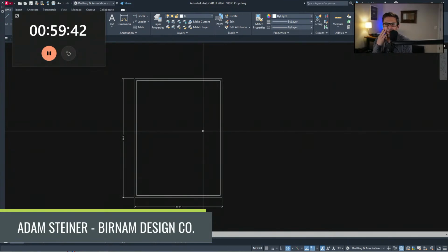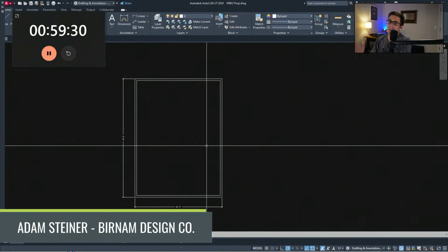So as weird as this sounds, typically I start with the bedroom area. I don't know, just blocking that off in my mind seems to make a little more sense, and then working backwards, kind of backing into the main living area. In this size, what I'm thinking, okay, so let's go through a couple parameters here. What I'm thinking with something this size is you're not gonna have room for a mudroom. You're not gonna have room for a dedicated laundry room. You're not gonna have room for a dedicated foyer. So the laundry is probably gonna need to be a closet, stackable somewhere in the plan. And then mudroom entry that probably is gonna need to be absorbed into that main living area somehow. Maybe we can create a little alcove or something for it, but it's gonna be cozy.